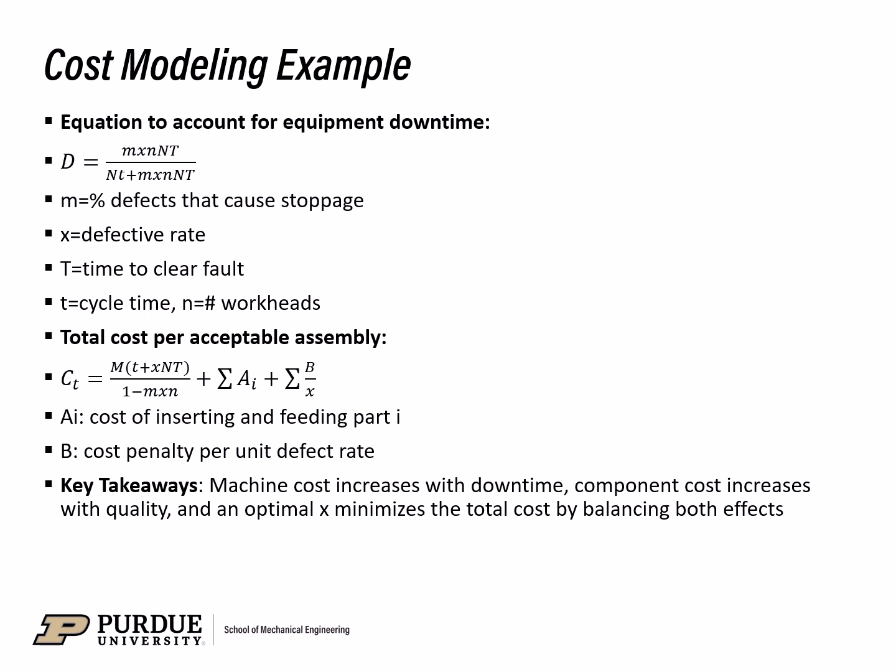So redesigning a feature can prevent that occasional misalignment, prevent that fault from happening. Let's say you add a bevel to reduce the part friction. This can end up being more economical than tuning out the defect through a final inspection.